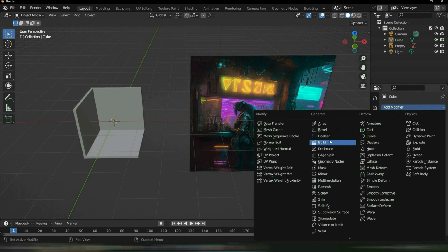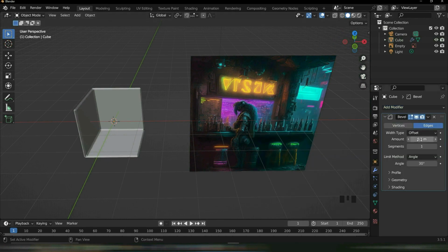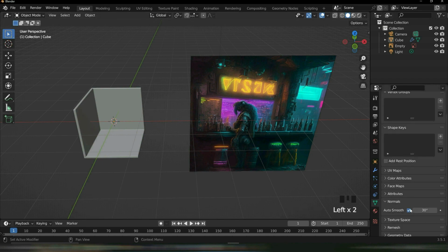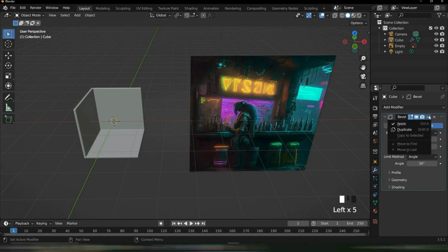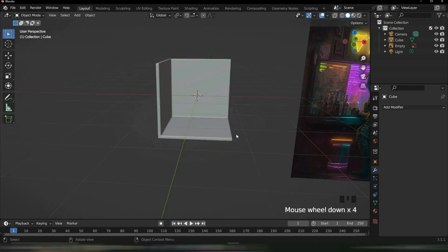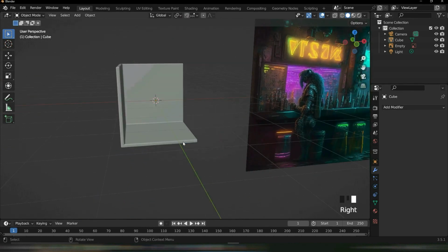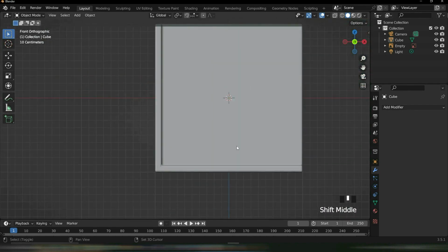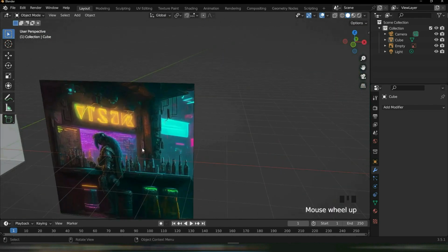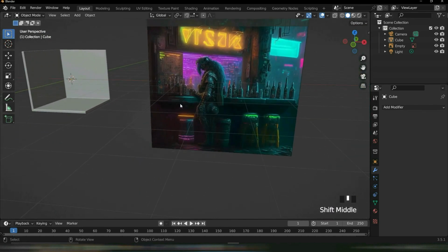Let's do a bevel modifier. Let's do 2 segments, and let's reduce it to 0.02. There we go. Right click, shade smooth. Go over here, click on the normals and do that. Back to the modifier, apply it, and it should look something like this. Looks pretty good. Mainly that's for when we press 1 on the numpad, so we can see the edge more easily. Okay, so let's get started with modeling a lot of the stuff.